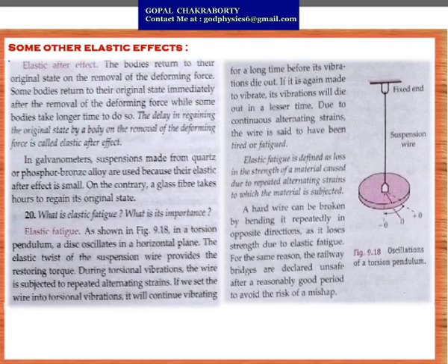If we set the wire into torsional vibration, it will continue vibrating for a long time before its vibration dies out. If it is again made to vibrate, its vibration will die out in a lesser time. So due to continuous alternating strain, the wire is said to have been tired or fatigued.